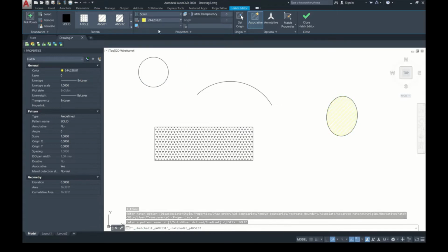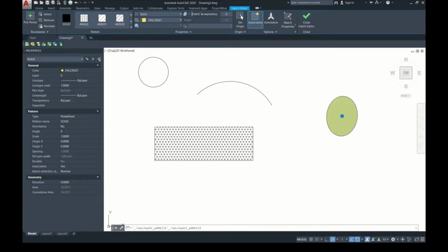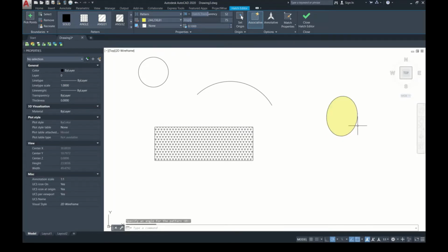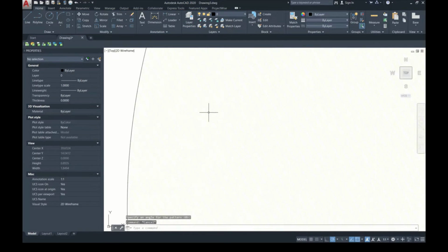Gradient also same. So here hatch transparency, while using drawing sheet it will give some transparencies, and you can control the angle of this pattern also, and scale. I will give 5, means this much. I will give 0.1, means it is too close lines it will come.